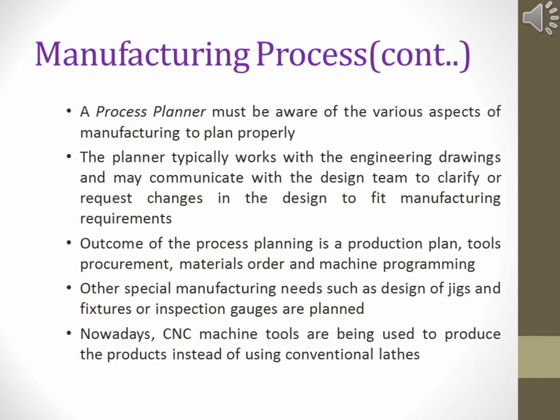Process planner. The one who is going to prepare the process plan must be aware of the various aspects of manufacturing to plan properly. The planner typically works with the engineering drawings and may communicate with the design team, because the designer may develop the design based on the customer's requirements. The requirements may vary from customer to customer. The process planner has to prepare the process plan to satisfy the design need. Otherwise, he can request changes in the design to fit manufacturing requirements.